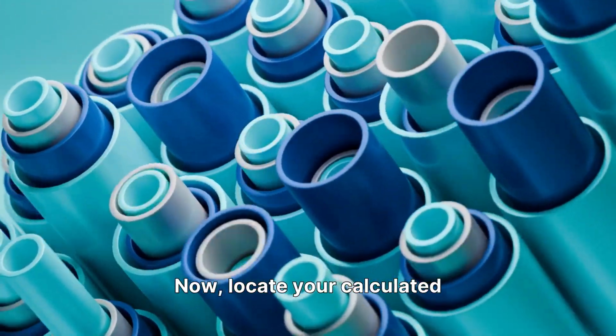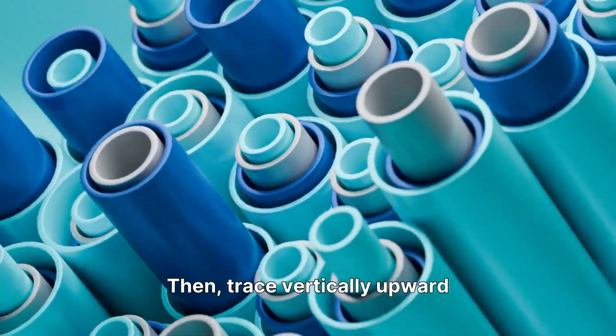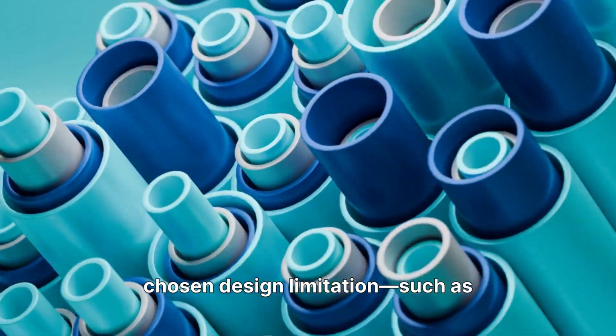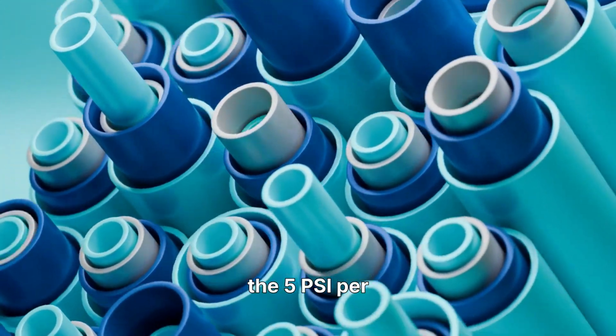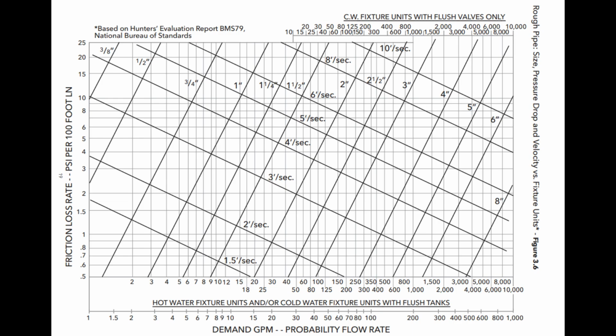Now, locate your calculated fixture unit count on the horizontal axis. Then, trace vertically upward until you intersect the chosen design limitation, such as the 5 psi per 100 foot friction loss line or your maximum velocity line. From that intersection, trace horizontally to determine the required pipe size.